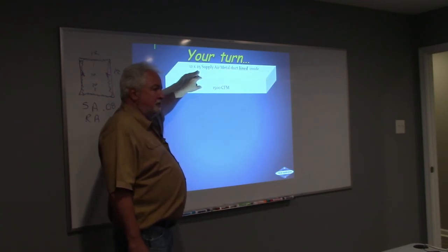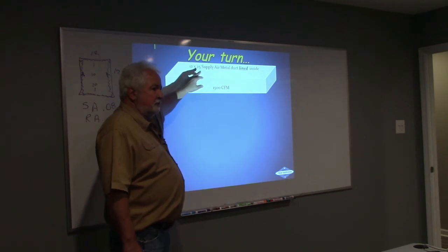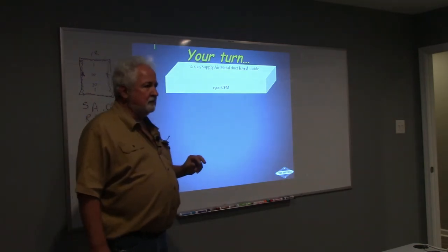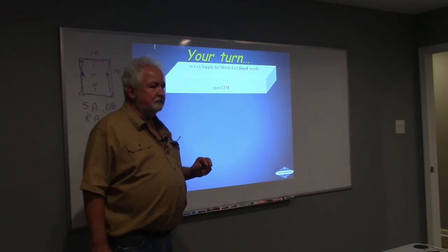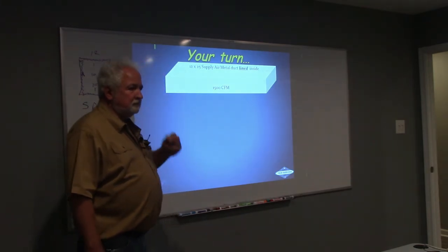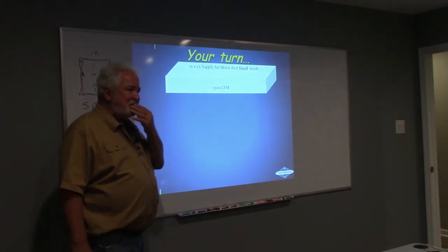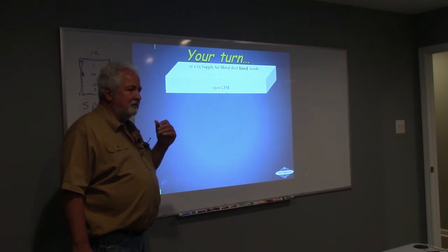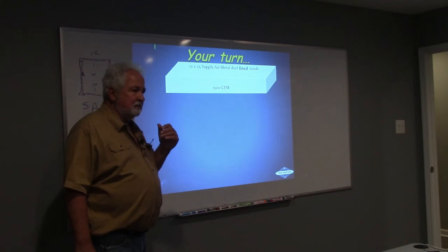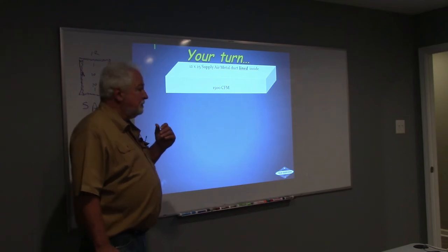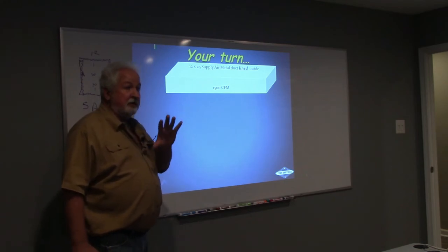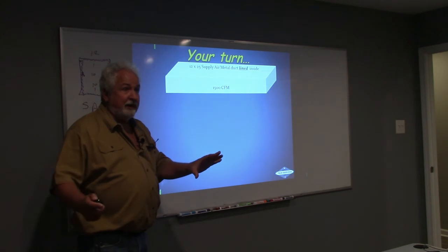Wrong. Why? 12 by 25. Because you have to go to this part of the chart. Rectangular duct. Okay. 12, right here. Match it up with that 25 number that's right there. So you got 12 by 25 duct. Yes, it is. 0.08, 1,500. Got it? Sweet. Okay, so we got duct with liner. You know where to go for that, yes?